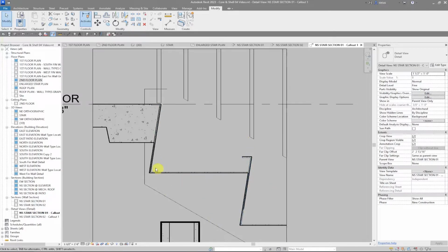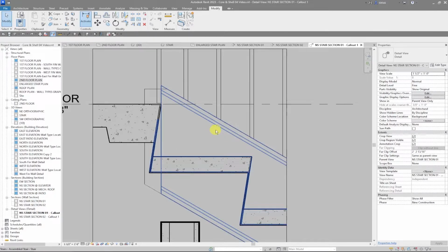And if I don't want to have to go back in here and redraw the stair with a concrete filled region, again, that's too much time. So what I could do, instead of hiding, I'm going to undo that. I'm going to use the line work tool. That's the modify line work tool right here, or you could just type LW. I can modify the lines that make up the edges of my 3D objects by using this line work tool. This only works on 3-dimensional objects.